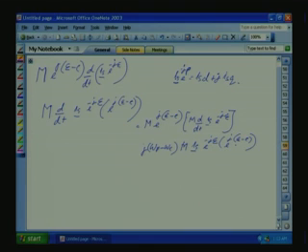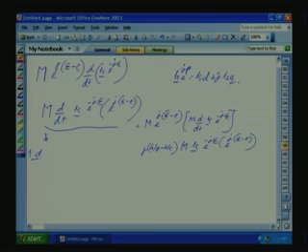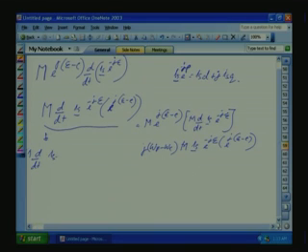Okay. This term we know it is equal to M into d by dt of ISD plus j ISQ, because these two cancel. Here also these two cancel. So this term is by bringing this one here. So this will be equal to j omega rho minus omega r into M into ISD plus j ISQ.